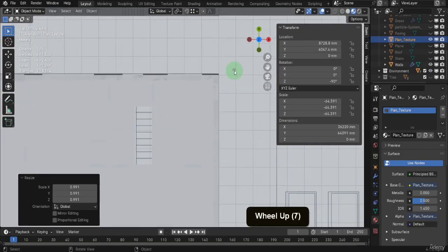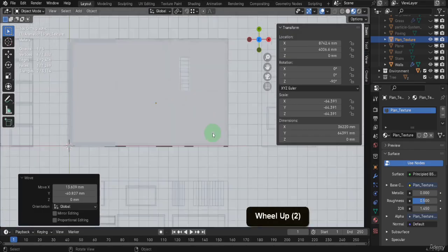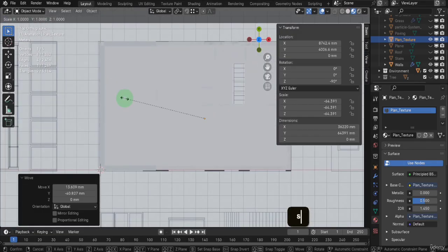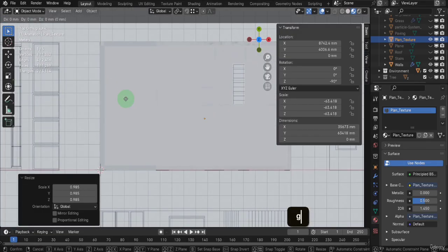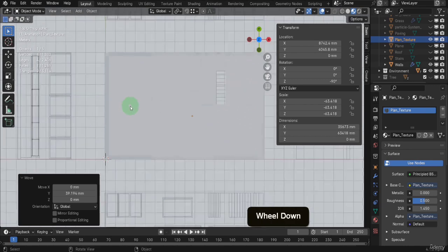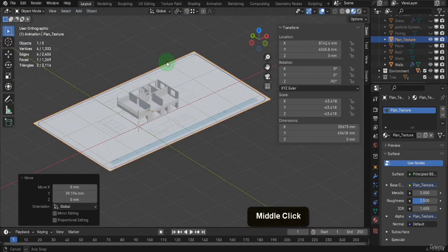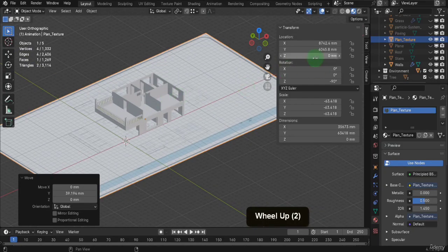If you zoom into the 4 corners, you'll be able to get this exact. Just make sure it's close and the 4 edges match all around. That looks good now. Next, we can position this on the Z-axis just above the tabletop. So in the Z location, we can input -201 here.